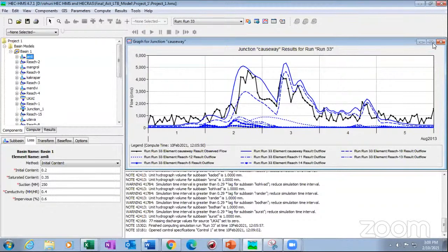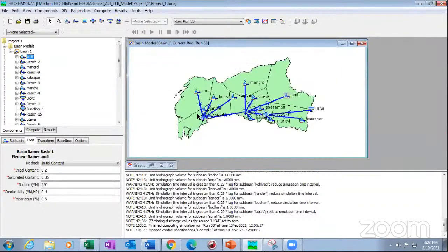But you can see that there are like 11 to 12 subbasins. Changing each of the small values and making the combinations might lead to 10,000 or more simulations, right? Because the first time I will change certain values at one subbasin and keep the others constant, like in a global sensitivity analysis. I'll go on doing all these things and come to the point where the model gives good accuracy, meaning the maximum accuracy we can achieve. But that is highly laborious, and no one expects you to do it that way.